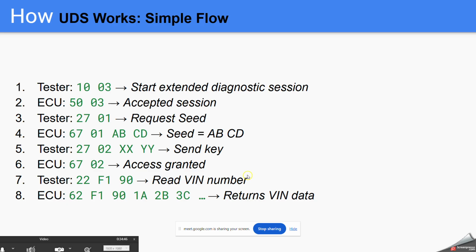You want to read some DID. DID is a diagnostics identifier. So each piece of diagnostics data will be assigned a unique 16-bit number, and that unique 16-bit number is any number that you have to define in your Candela file, or it has to be agreed between you and the customer. And then we will also have some standard DIDs, which are agreed and accepted overall in the UDS standard, like 14229 is the UDS standard. So that is also possible. So based on the DIDs that we have with the customer, or we can have some proprietary DIDs also with respect to your own implementation, those numbers we have to give accordingly.